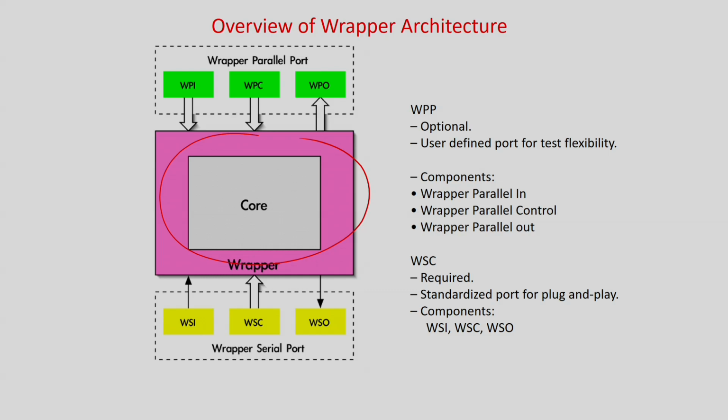Everybody will be connected through a single TAM mechanism and a single standard architecture. So I have to maintain a protocol. If I have a different wrapper, you have a different wrapper, and he gives a different wrapper, and I have to put them in a single core and test it together, it can be a problem. Therefore, while designing the chip with a wrapper, I have to follow a particular standard of accessing all the core pins. So people also design and manufacture in that standard format.